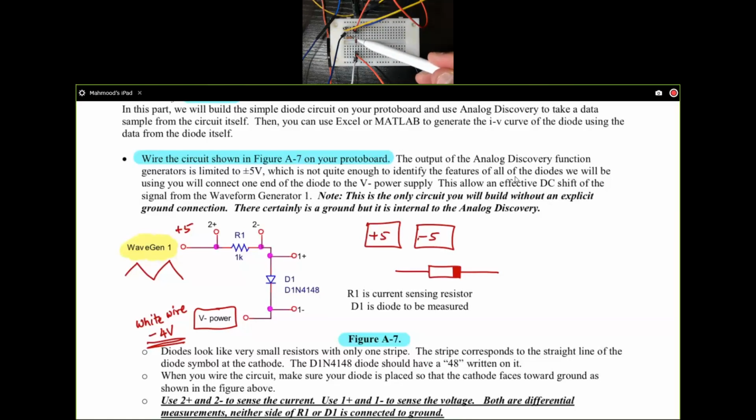It has an orangish tinge to it. In very small letters, there is 1N4148 written on it. But what I can clearly see is that there is a black ring on the bottom side of this diode, and that is the negative terminal or the cathode, which is why I've connected it away from my resistor.